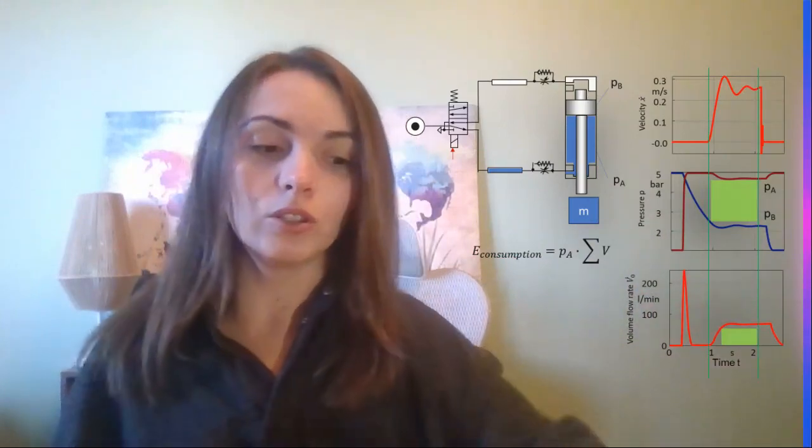Those kinds of technology are now available, and they can actually adjust, using just one standard cylinder, this input energy to different forces: 200 newtons, 500 newtons, or 10,000 newtons. We still can use the biggest cylinder, but we can limit the volume flow rate that we put into the cylinder according to the task.